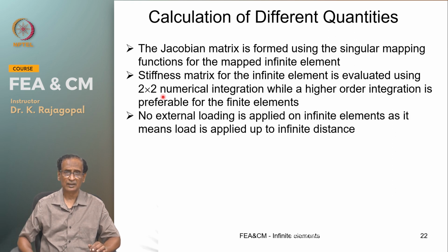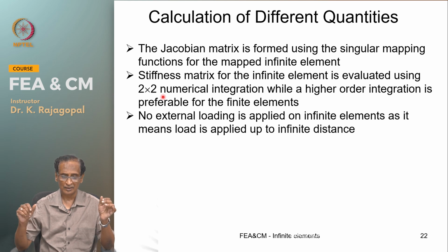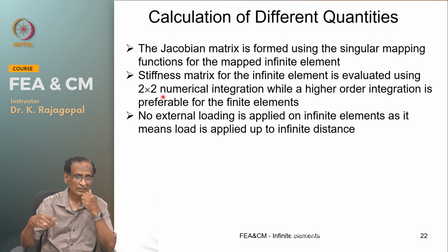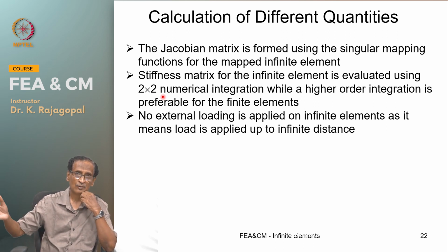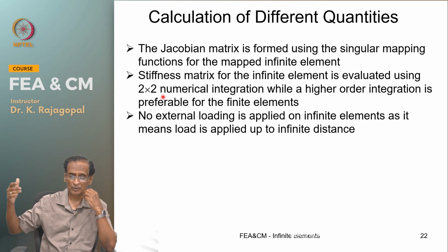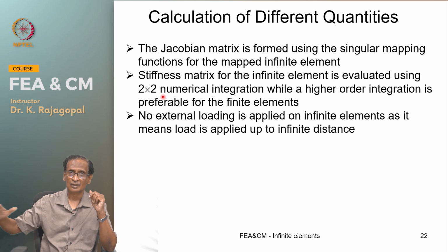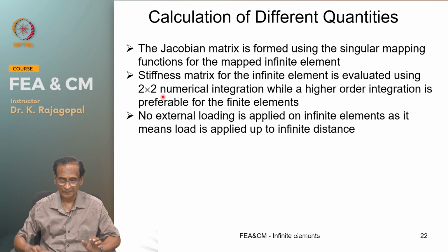And we should not apply any external loading on the infinite elements, because if you apply any external loading, either a uniform pressure or a concentrated load, that means that your loading is applied up to infinite distance, because our infinite elements are basically representing a semi-infinite length.